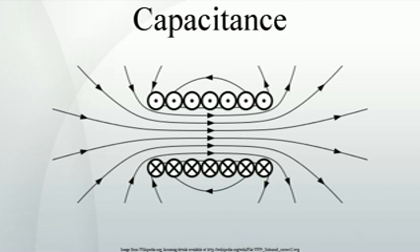Another example of voltage-dependent capacitance occurs in semiconductor devices such as semiconductor diodes, where the voltage dependence stems not from a change in dielectric constant but in a voltage dependence of the spacing between the charges on the two sides of the capacitor. This effect is intentionally exploited in diode-like devices known as varicaps.